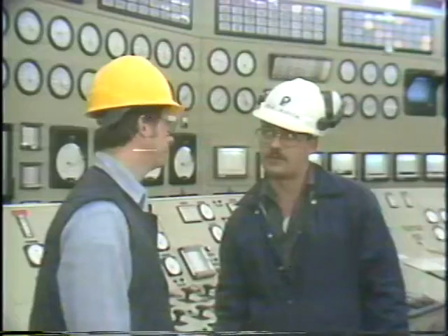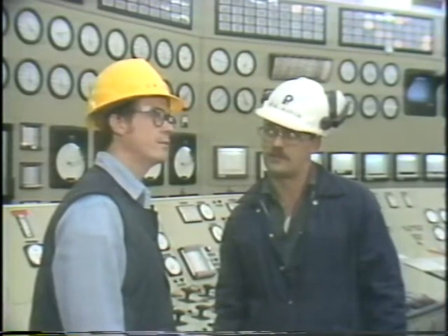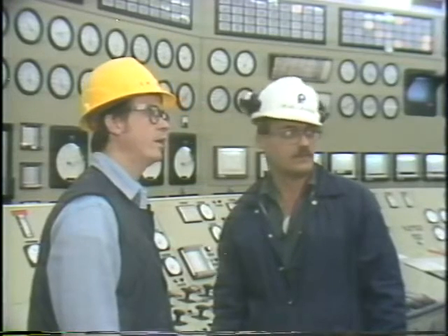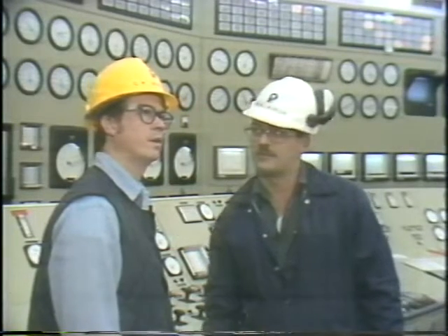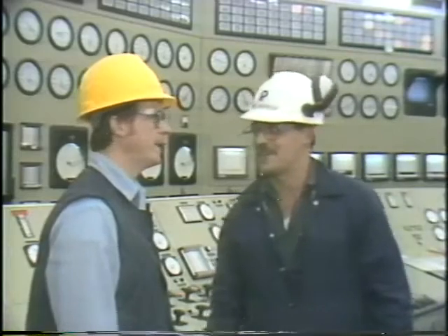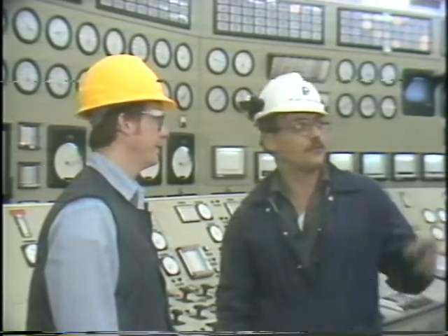Now, all of these are the kinds of questions that you can ask the operator. That will give you clues as to the nature of the problem. And while you're talking with the operator, observe the system's indications. From your knowledge of the plant, the prints, and your talk with the operator, take a look at the indications on the instrument panel. Check out the alarms, the gauges, the recorders, anything that'll give you a visual indication of how the system's operating, so that you'll be able to recognize as many of the symptoms of the problem as you can.